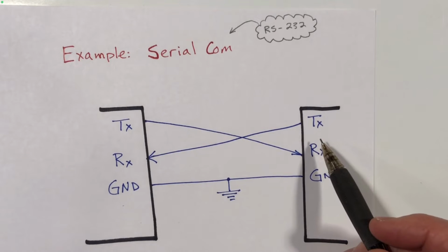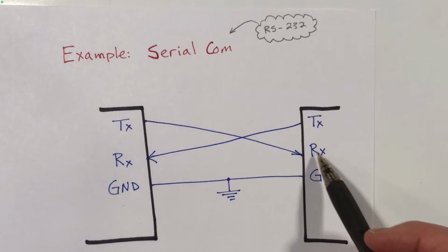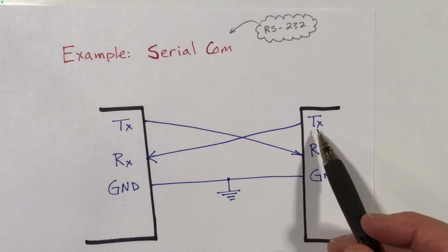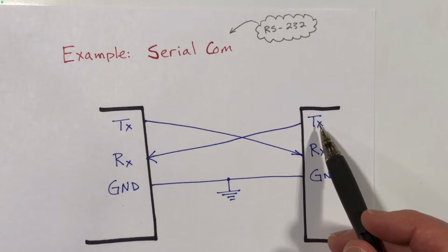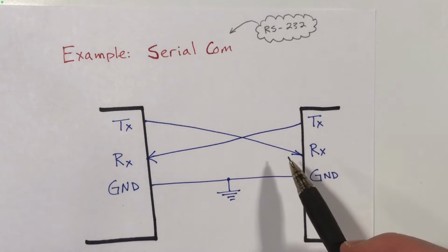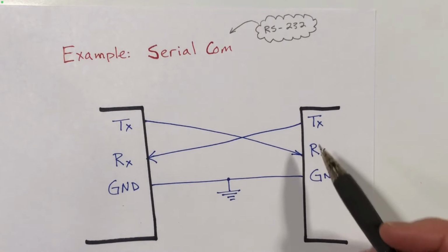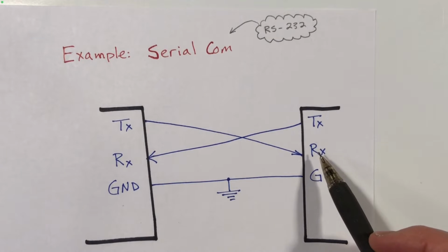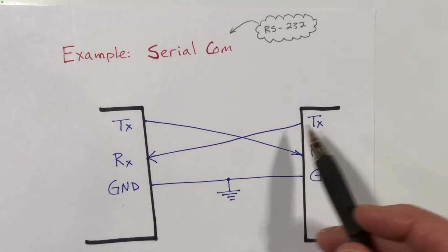If you are familiar with Arduino, the transmit and receive signals are available on pins 1 and 2. Every time you do something like a Serial.print, you will transmit on the transmit pin. Of course, the Arduino also sends the communication over the USB connection, and you can see it in your serial monitor window, but that's another story.